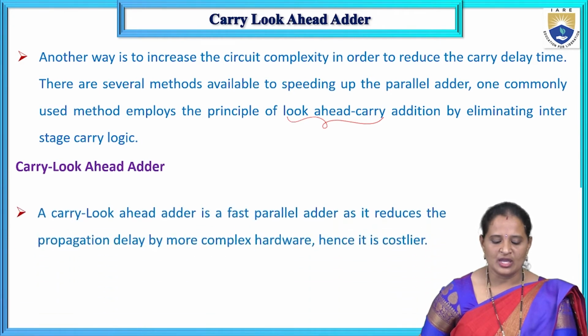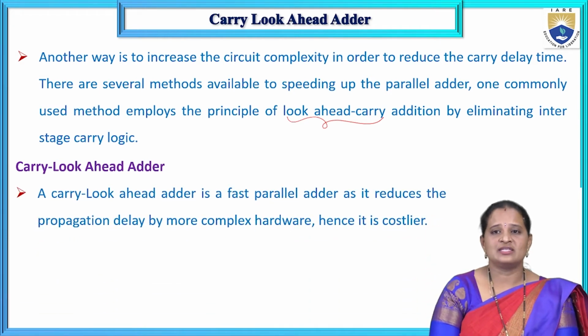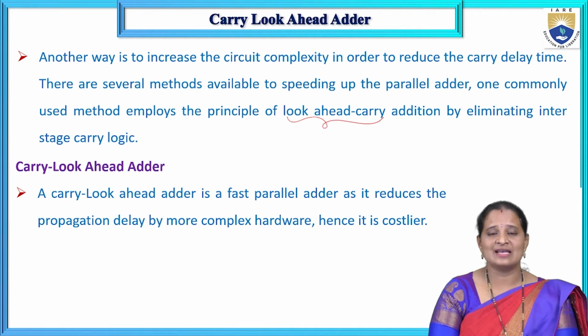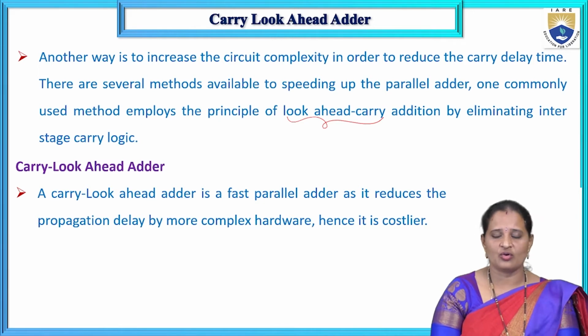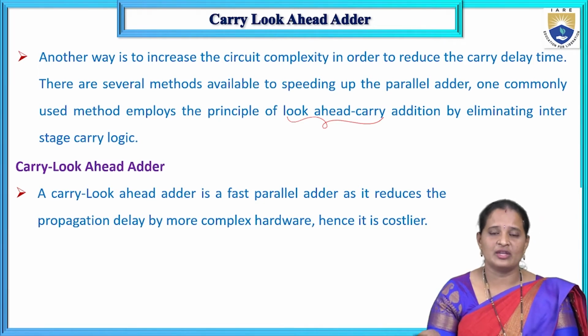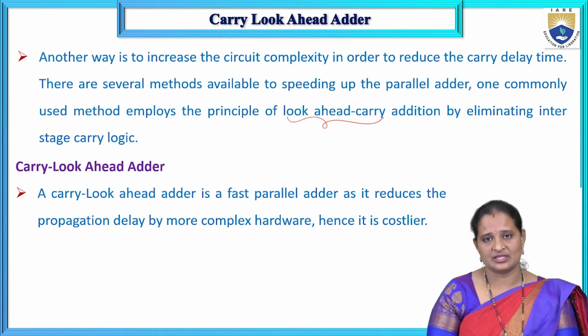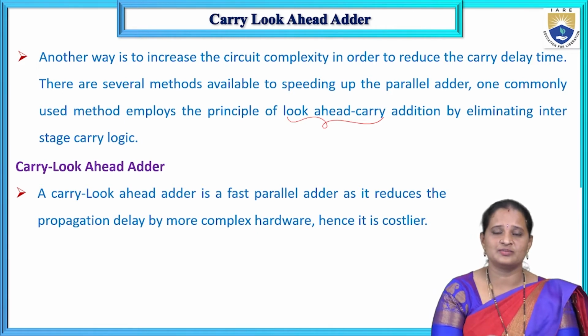We'll see now. The carry look-ahead adder is a fast parallel adder as it reduces the propagation delay by using more complex hardware. So it has a drawback: it increases the circuit complexity, but it increases the speed of operation. As it increases the circuit complexity, it is also costlier.